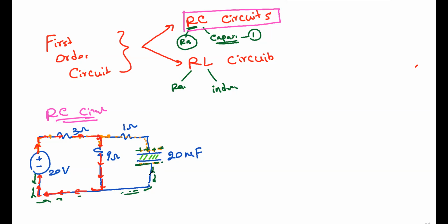Yeah. So now after some time, the capacitor will be fully charged and no more electrons go into the capacitor. All the electrons will flow in the opposite direction. So the red arrows are for the conventional current. Conventional current is opposite to the electron flow. We have discussed this in the first week, if you can remember. So the green arrows are for the electrons. We normally show the current flow, not the electron flow. That's why I drew the red arrows, which is our current.